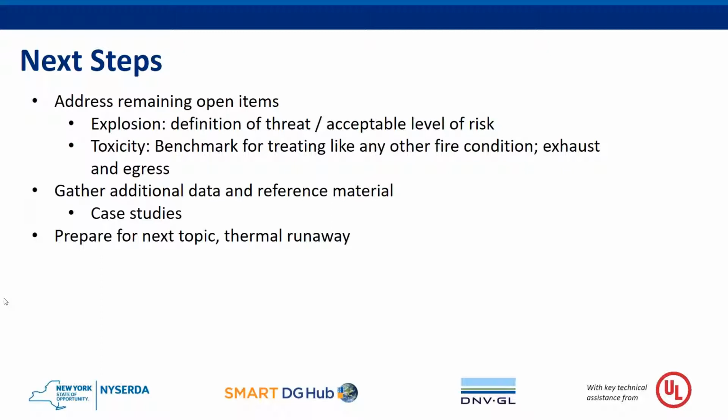Now, back to what you just asked. Again, I'm making some assumptions here. I've got a common cell, we're going to call it cell model 1. We use cell 1 in modules, and I may have a variety of numbers of cells in a module. I may have 10, I may have 20, whatever. When I'm testing a module, if I test the 20-cell module, I'm going to say that applies to the 10-cell module because I've got a worst-case scenario.